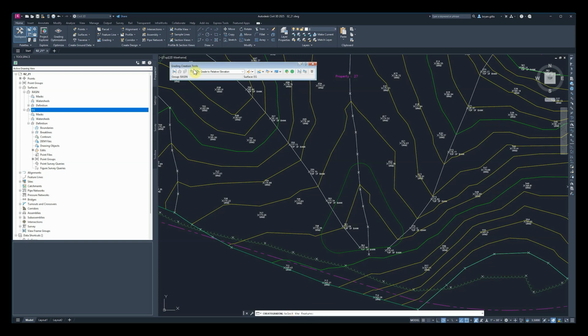And now, after we've done all of that prep work, making sure our settings, our surfaces, everything were correct, we're going to get into the process of creating grades. So let's select this feature, which is supposed to represent a basin. The first thing it's going to do is ask us to select the grading site. We can click somewhere here in the center as a mid site within our feature. Then it asks, do we want to apply it to the entire length? The default is yes. Let's hit enter to accept that default.